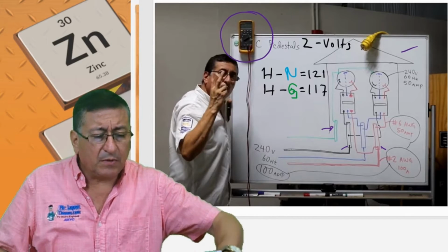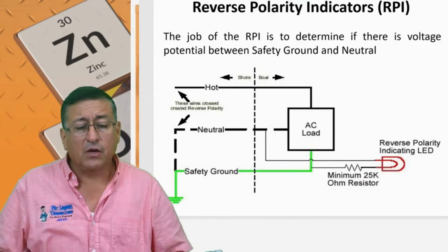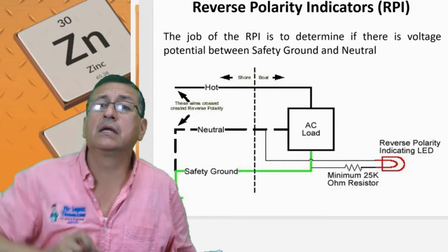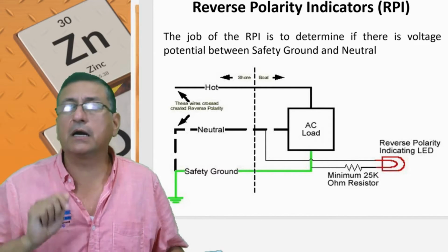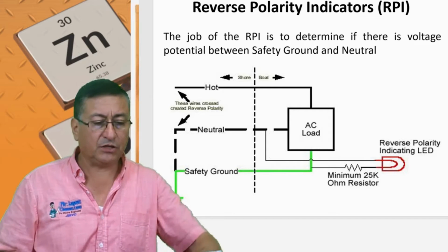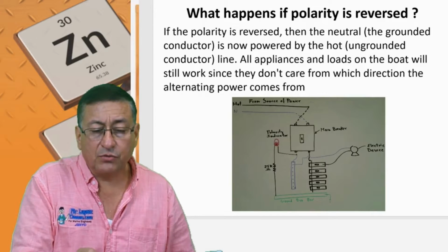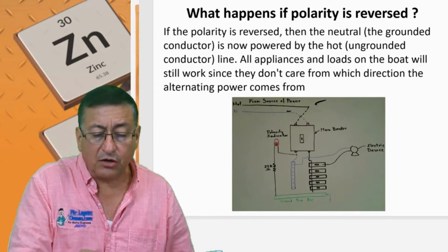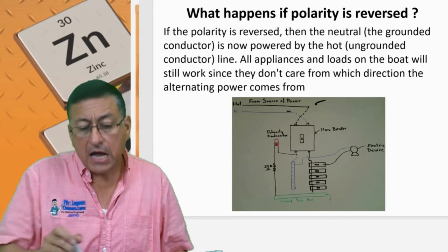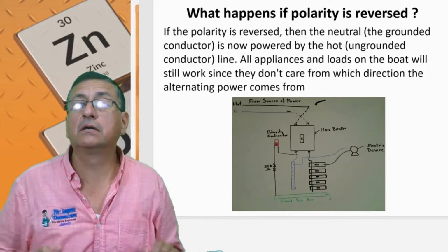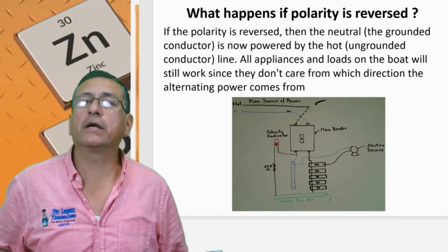You remember the phenomenon of a reverse polarity, and it's basically when you have a switch, the neutral and the hot line. The hot line enters into the neutral bus bar, and the neutral enters into the group of breakers. That situation. Yeah, you remember that situation? You have a switch, the hot and the neutral. And now the neutral bus bar is hot. The neutral bus bar is hot. And the breakers interrupt right now the neutral, not the hot, because you switched those wires.